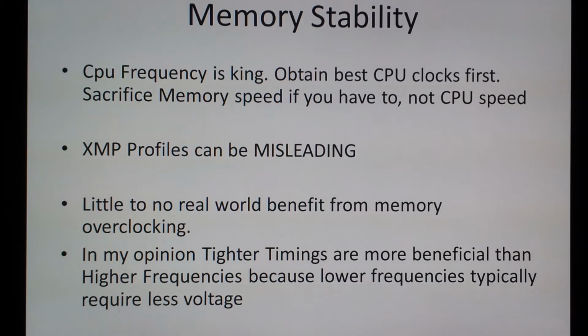However, I personally like to overclock my memory. I like to give it a lot of volts. So if you're into overclocking in gigahertz, yeah, give it volts, give it frequency, do what you got to do. If synthetic benchmark values make you happy, by all means do that. I do it personally as well. But overall, if I were to suggest something, I would say go with lower voltages, tighter timings, and don't overclock the memory frequency.